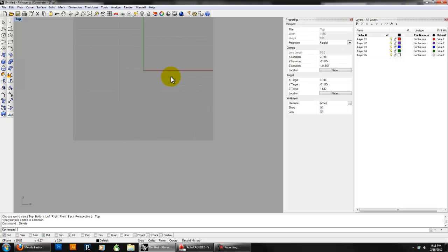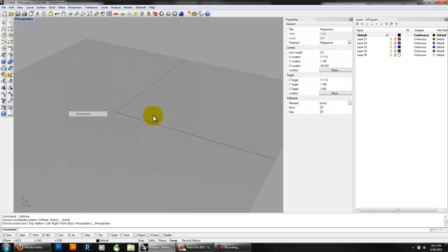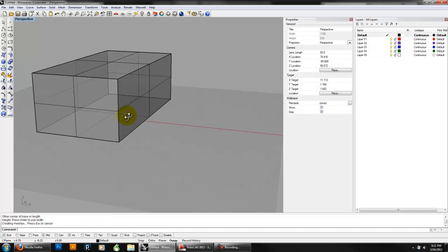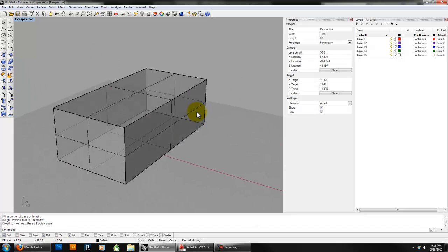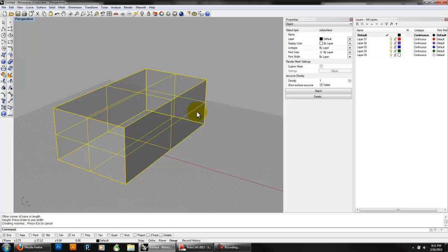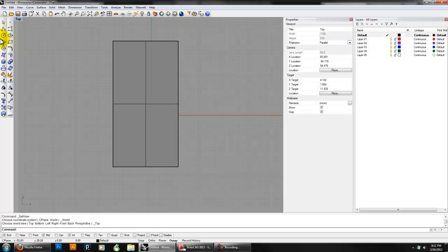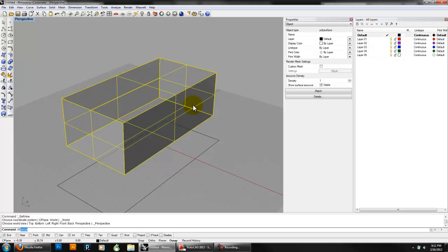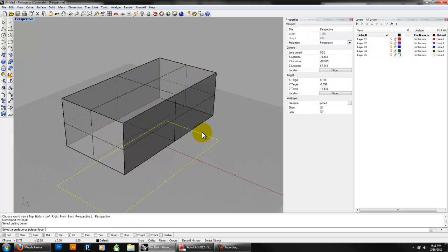So lots of interesting combinations, and we'll talk about this in class. But another thing you can do is to take your massing model. Let's assume this is your model, and you can do a thing called a wire cut. So let me just make a line. You take your thing and say wire cut, and the cutting curve would be this.